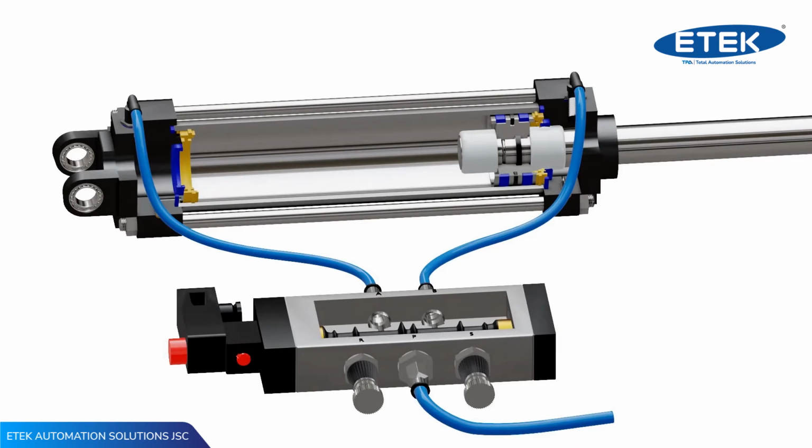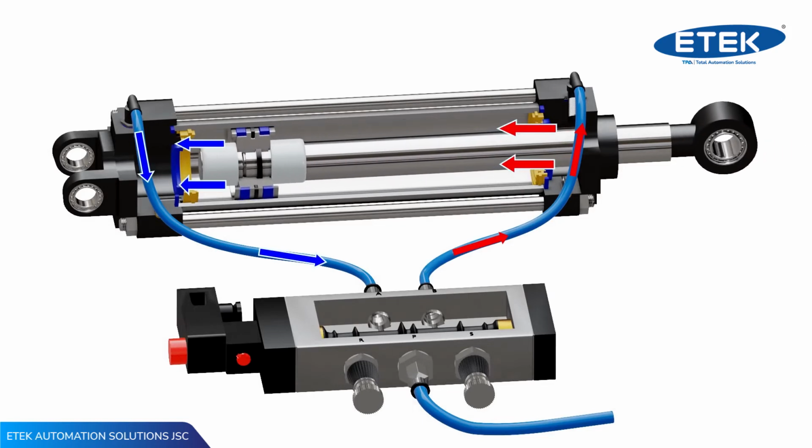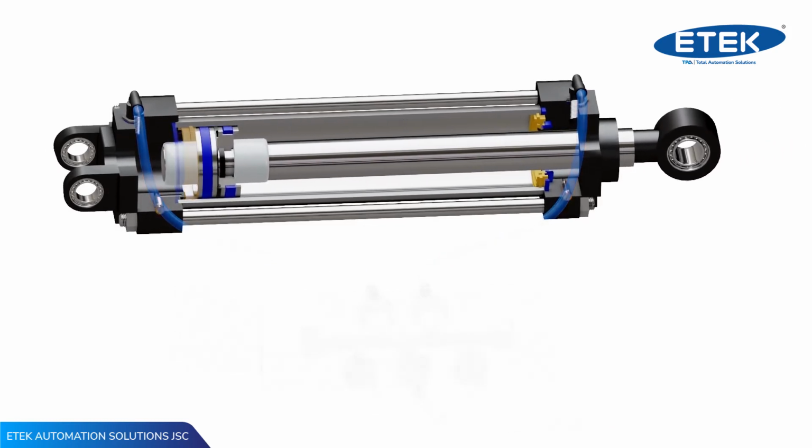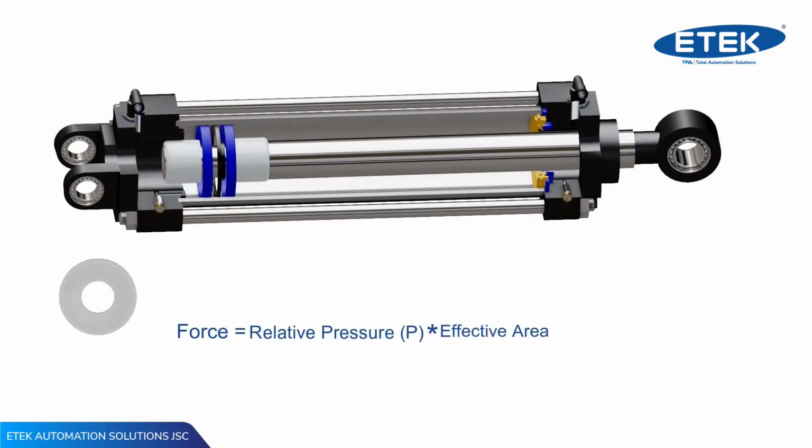During a retraction stroke, the valve directs compressed air to the head end of the cylinder. This causes the piston to return, and air in the other chamber escapes from exhaust port R. The theoretical force of the actuator is the relative pressure on the piston multiplied by the effective area of the piston on which pressure is exerted. Here, the relative pressure is the pressure of supplied air minus the atmospheric pressure.